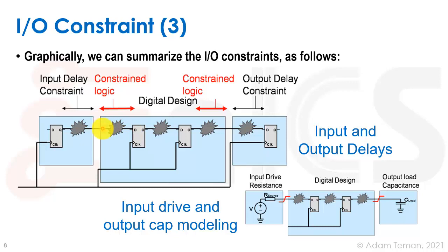Usually, we design with a timing budget. We know that whoever is designing this thing outside has, let's say, half of the clock cycle, and we have about half the clock cycle. So if our clock cycle is 1 nanosecond, let's say set max delay half a nanosecond and try to meet half a nanosecond on this path.